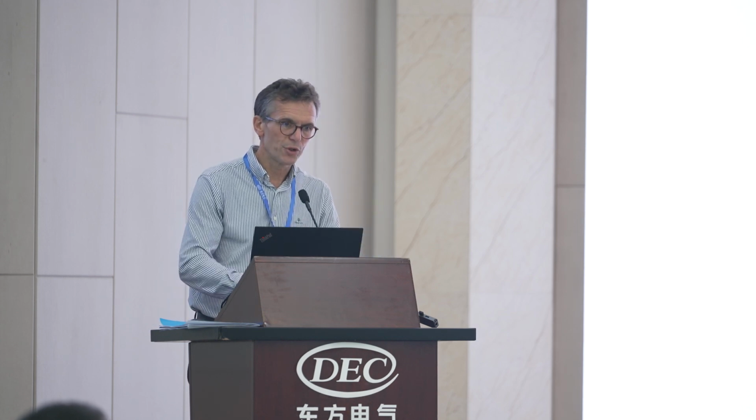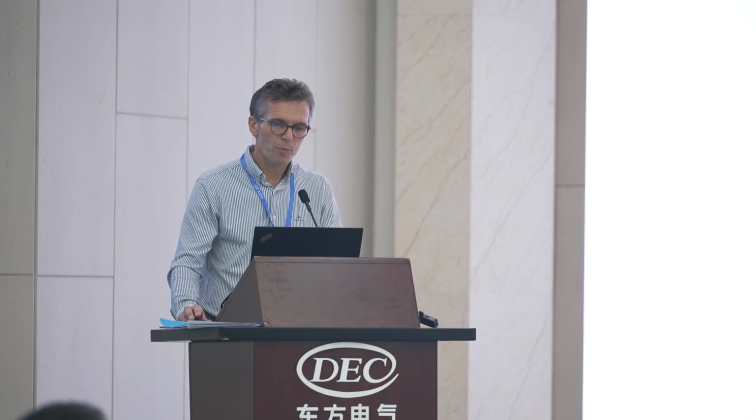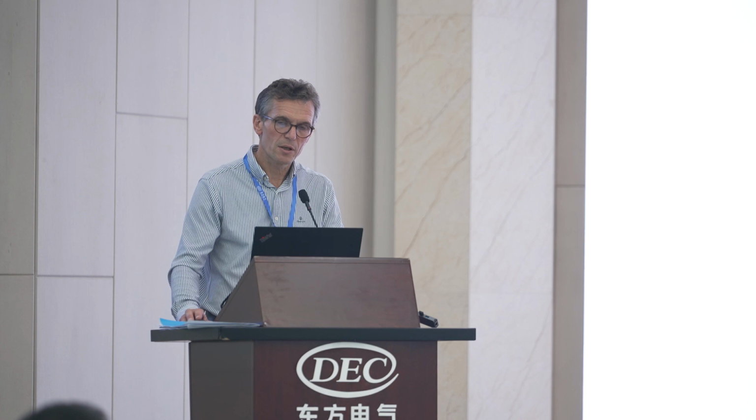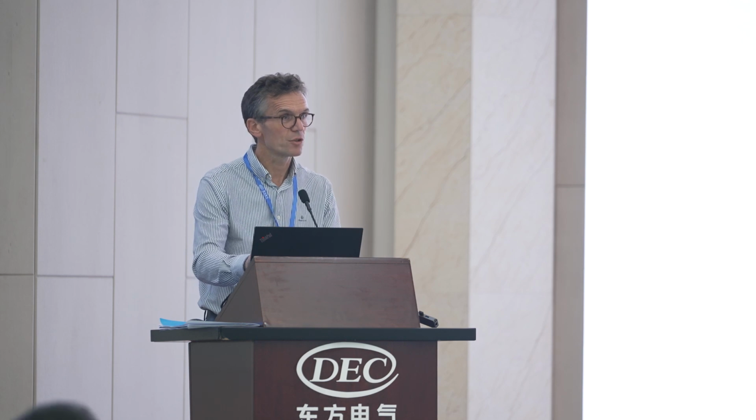And I just show this figure of results. This is the carbon capture efficiency. What we see here is that in our unit, with this rather simple design, when we are operating on biomass fuels, all the three oxygen carrier candidates can give us very good results, very high capture rate in fact. But when we start to fire pet coke, this breaks down. We don't have the residence time needed, and we don't have the carbon stripper needed, and this is exactly what we have in the European configuration in the CHEERS project to manage such a difficult fuel.